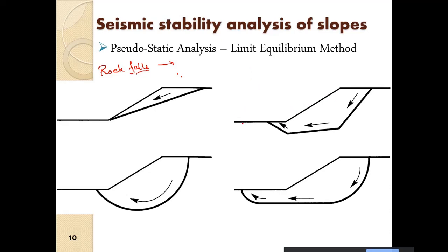It is mainly on moderate kinds of slopes, and it is somewhat of lower velocities. And then there are lateral spreads. Lateral spreads occur on very gradual, low-range slopes, and they generally involve liquefiable soils. So when there is a gentle slope and the soil liquefies, the soil flows, and we have the lateral spread. Of course, we will analyze those also, when we analyze the displacement analysis of slopes.